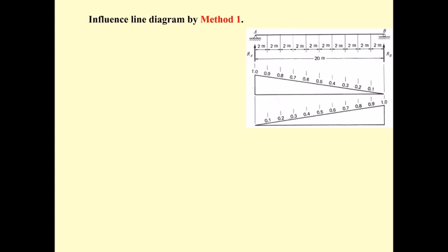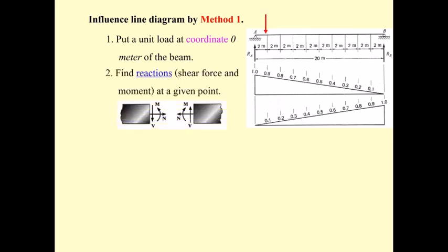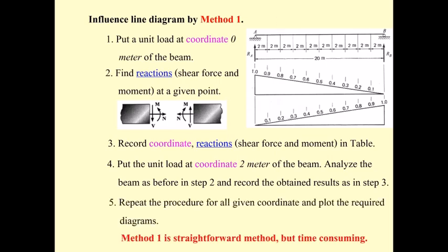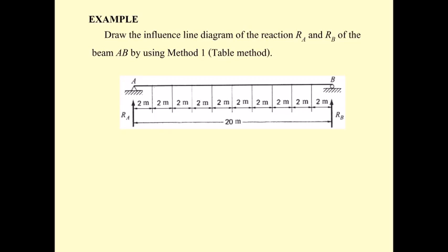In method 1, you move the force step by step. Then we compute the reaction for each loading step, and then we move another step and compute the reaction or the shear and the moment for the second step, and then we move step by step like that and do the same thing. The method is very straightforward but very time consuming. Let us consider this example.